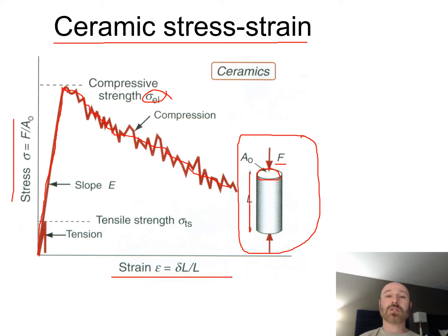So a lot of the work we did was with bridge decks. Now with bridge decks, you have rebar embedded in the concrete, so that's exactly what we did. We made some test specimens with various types of concrete that we then put on a tensile testing machine where we gripped the two ends of the rebar and pulled it at a slow rate, and then took a look at our tension testing and our load versus deflection, and in turn our stress strain graphs related to that there. So that's not very common.